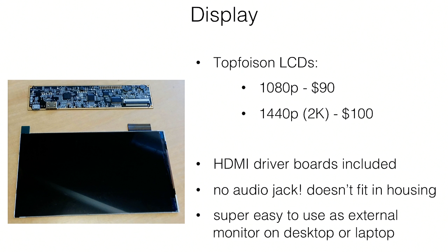Without the driver board, it's very difficult to drive them. With the driver board, you just plug in an HDMI cable and it runs. Okay? If you get the driver board, don't get the audio jack. The driver board has an optional audio jack that is mechanically very awkward and makes it difficult to fit into the housing, so we usually get them without.